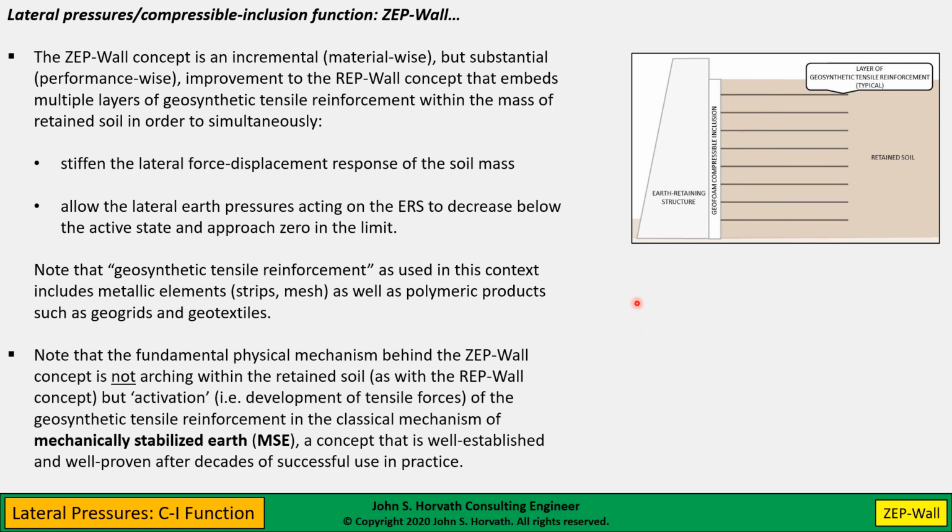Well, it's important to understand the fundamental geomechanism going on with the ZEP wall concept is not arching, as with the rep wall concept, but as I said, activation, if you will, of the geosynthetic tensile reinforcement in the very classical mechanism of mechanically stabilized earth. And this is a well-established, well-proven behavior from decades of successful use in practice and associated research. So what we're doing here is nothing new. The only new element is we're using the geofoam to allow the reinforcement to activate.